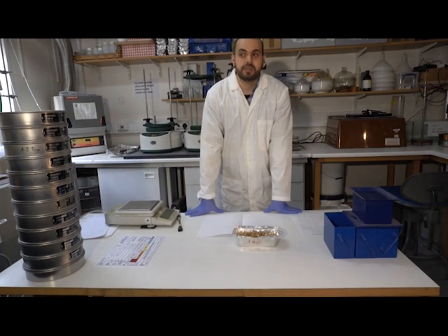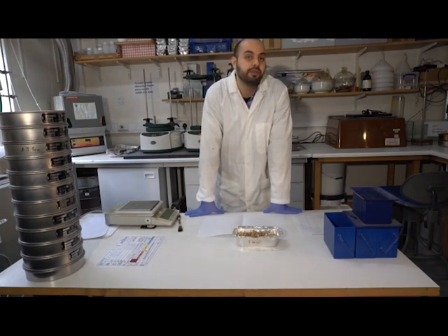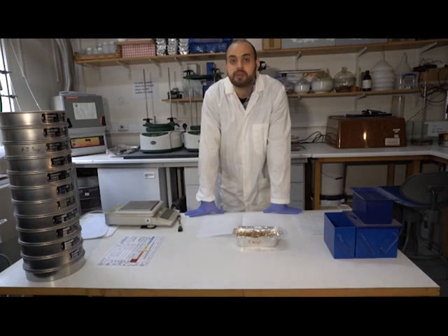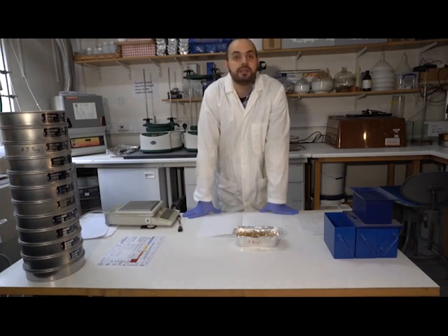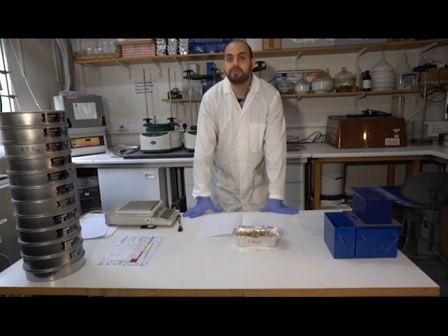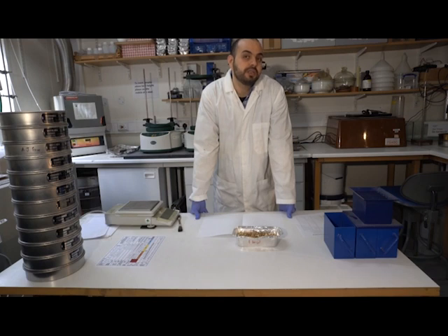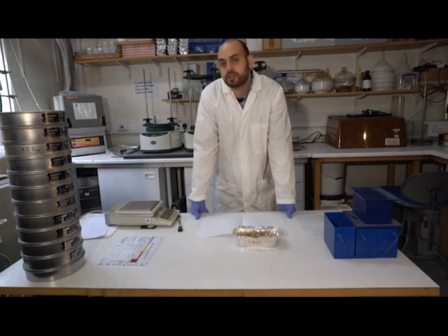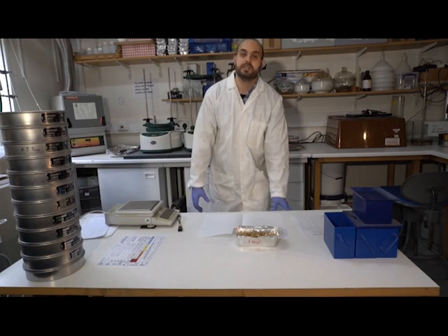If we also want to describe sediment movement, for example, how waves move sands on beaches or rivers move gravels on their bed, then again, the mode of transport and the rate of transport are also a function of that sediment size or soil size. And so the particle size distribution really gives us a very powerful statistical tool that will allow us to use conventional empirical equations to describe water flow through porous medium, sediment transport rates, or even soil bearing capacity.